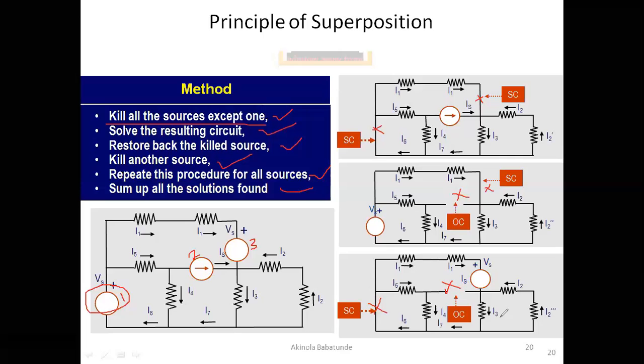And now we would have 3 major equations on our ends that we can work with to find the exact response to the circuit. So in many cases, that simply means here you're going to have I1A, I1B, I1C, I2A, I2B, I2C, VSA, VSB, VSC. Okay, you're going to have all of those in all of those 3 equations, and as many of those A's and B's that you can have for all the currents and sources that we have in the circuit. Those are the things you're going to have. And with that, you will be able to analyze the circuit completely at the end of the day.